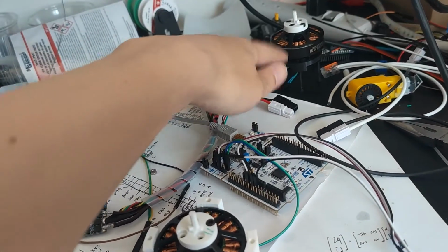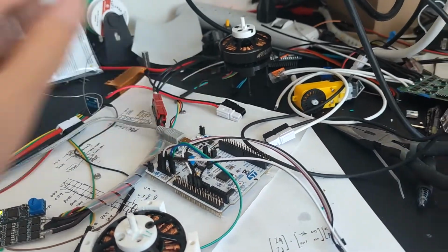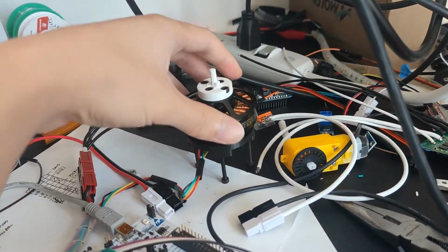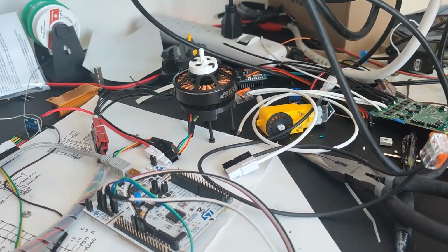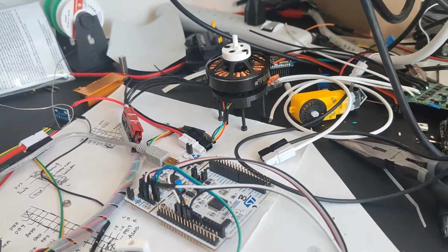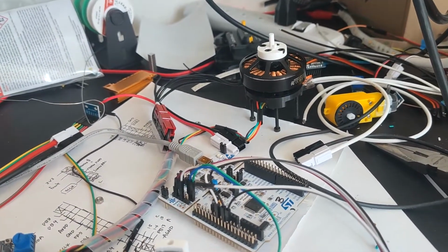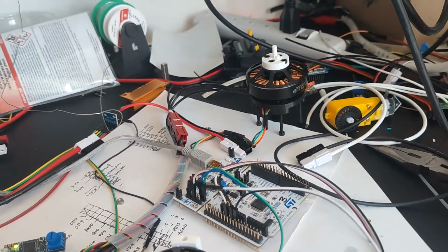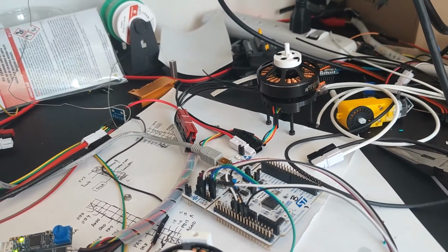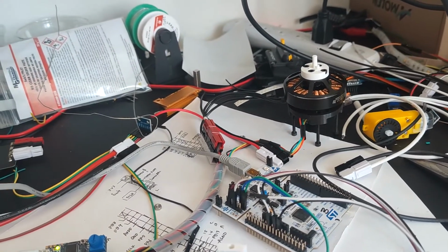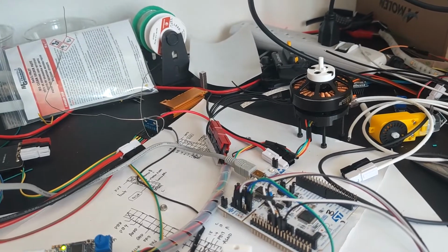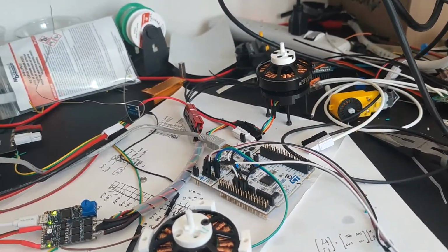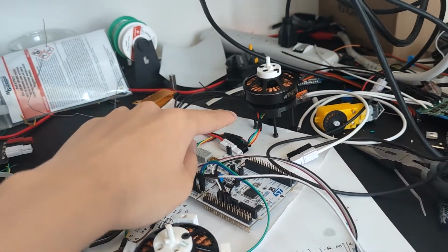The first one is the pull-up resistor on the encoder board. This is the board from Amazon, and I forgot what value they use for the pull-up resistor, but for high speed fast mode plus, I think it requires pretty low resistance, like 1K or even 270 ohms, 417 ohms, so pretty low. The normal 10K pull-up won't work here. So that is a thing to fix.